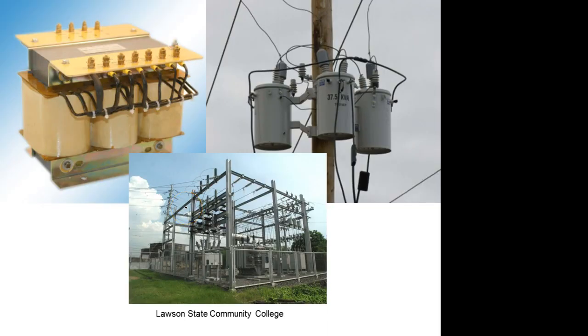So we can buy three-phase transformers, but usually Alabama Power does a lot of these on single-phase. And why is this? This costs more to install, but this is a lot cheaper to maintain. On a three-phase transformer over there on the left, if it goes out, by George, you got to replace the whole transformer.